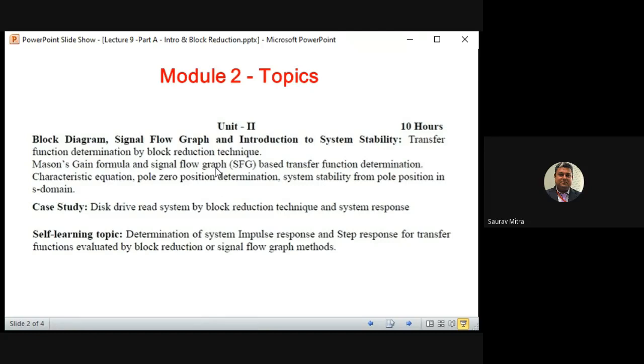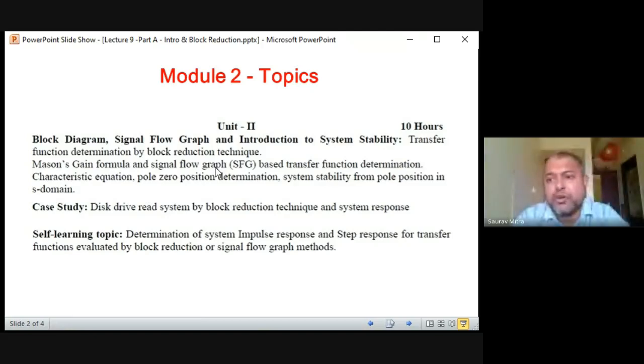Now if I'm giving a unit step input, X(s) is equal to 1/s, because 1/s is the Laplace transform of u(t). So if I'm giving the input to the system as u(t), then Y(s), the system output, will be X(s), that is 1/s, multiplied by the transfer function polynomial. If we take the inverse Laplace transform, then we can find y(t).